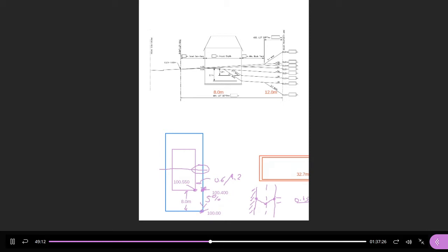Now consider this red line, from the corner of the building to the front corner of the lot. I'm going to assume, because the width is so small, that the length of this red line is about 8 meters. Everybody agree? I'm stretching it a little bit, but it's going to be very close to 8 meters. So now let's do the math. What's the slope of the red line? Well, I know the elevation here. The difference is the rise. Divide by 8 meters, the run. What's the slope of this red line?